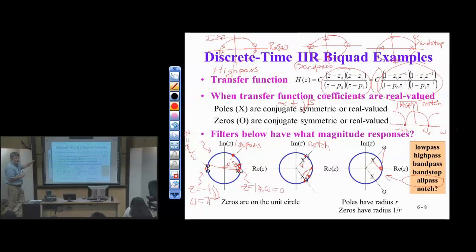It's just a matter of solving for C by plugging in Z equals 1, which is the DC response. It's one equation, one unknown. And just in case you need to pick something fast, C equals 1 is a good choice to start with.